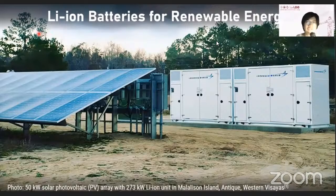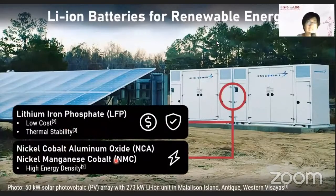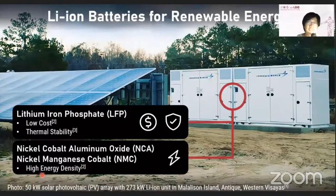Lithium-ion batteries are ideal for this purpose because they come in a variety of chemistries with various advantages. For instance, the lithium iron phosphate or LFP chemistry offers low cost and thermal stability, whereas the nickel cobalt aluminum oxide or NCA, as well as the nickel manganese cobalt or NMC chemistries offer high energy density.